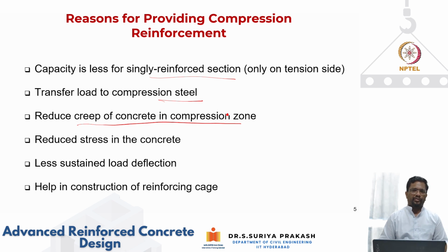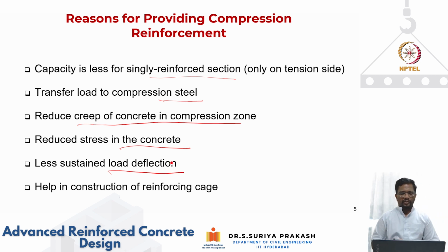We've talked about what creep of concrete is. Under constant stress, the strain in concrete in compression will keep on increasing over a long period of time. We talked about basic creep, drying creep, and so on. The effect of creep can sometimes be quite significant, and that is going to increase your long-term deflection. So to reduce the creep, one way is to put more compression steel. And again, as we've said, sometimes we want to reduce the stress in the concrete in compression, and we want to reduce the sustained load deflection, which we will discuss in the coming slides.